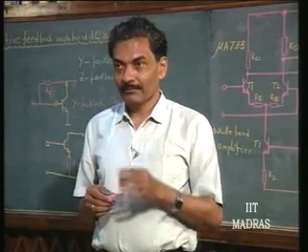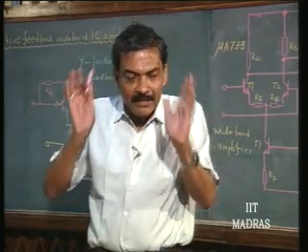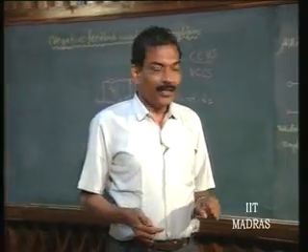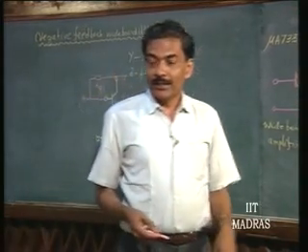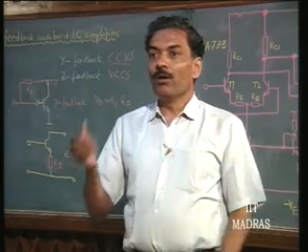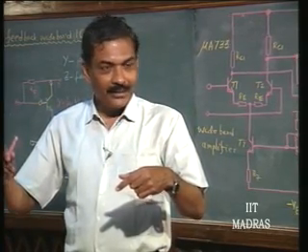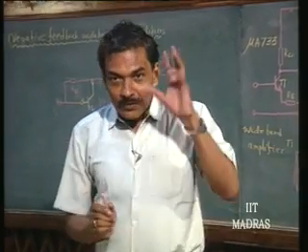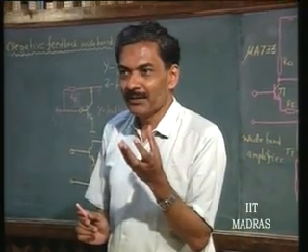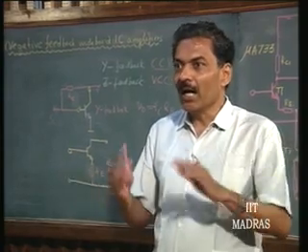Trans resistance in the Y feedback case is going to be reduced by the loop gain. Correct. In the case of any feedback, please remember, you are going towards idealization. What is idealization? If it is Y feedback, it is going to become a current controlled voltage source. That means the modified thing is the Z parameter. In the Z parameter, all the other parameters will go towards 0, only the forward transfer parameter will go towards a smaller value than originally, by the extent of loop gain. Going towards 0 of the other parameters is also by the extent of loop gain. So, this is a simple way of remembering things without faltering. In terms of parameters, if you remember, you will never commit mistakes as to what gets modified and by what extent.